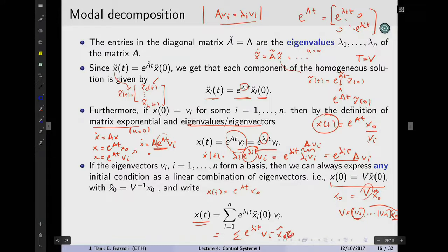This initial condition, this modal, this weird thing that came out from this transformation, you can simply imagine as a weight on each of the eigenvectors. Basically what we're saying is that if you take a system and choose any random initial condition, you can transform that initial condition into the favorite directions of the system. After this transformation, it's as if you're poking the system on its favorite directions, favorite defined by: if you poke it only there, it will respond only in that direction. You're poking it now in all these directions, but giving different weights on how much you poke each one of these directions. And these weights are represented by these x tilde i's.